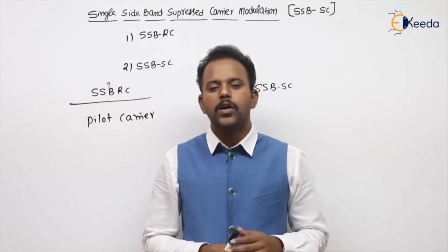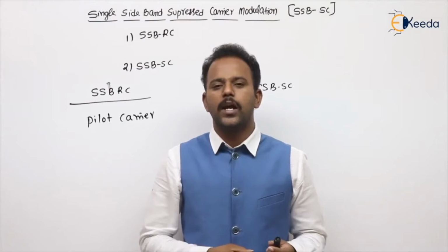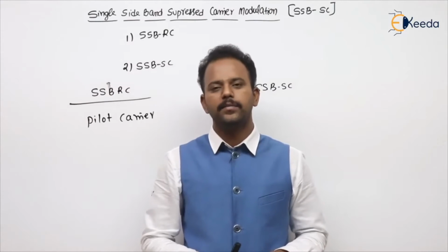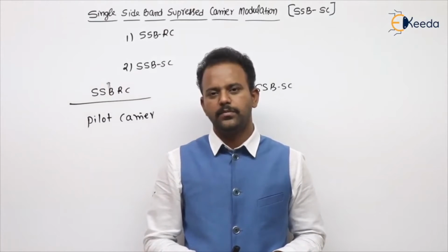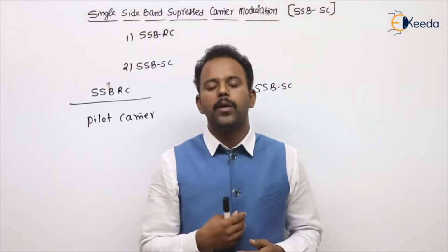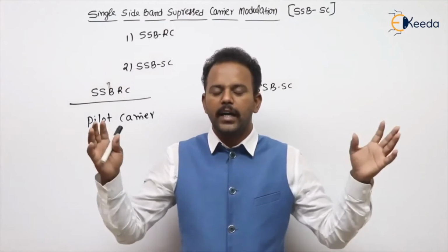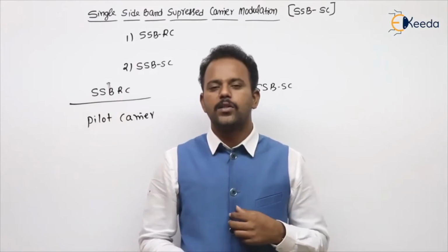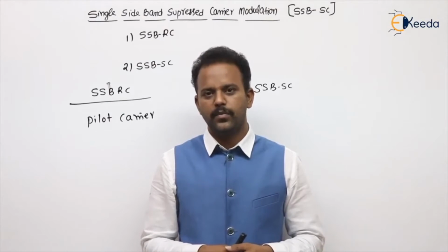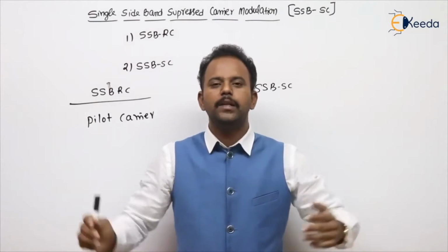Do you understand my point? So in the local oscillator we need a highly stabilized local oscillator which has to match the received SSB-SC carrier. In olden days, maintaining that was a problem. We didn't have such devices at that point. So maintaining a highly stabilized local oscillator in the receiver was a big cost and a big problem. On the transmitter side, anyhow we have to maintain it, but this much circuit you cannot keep in the receiver.